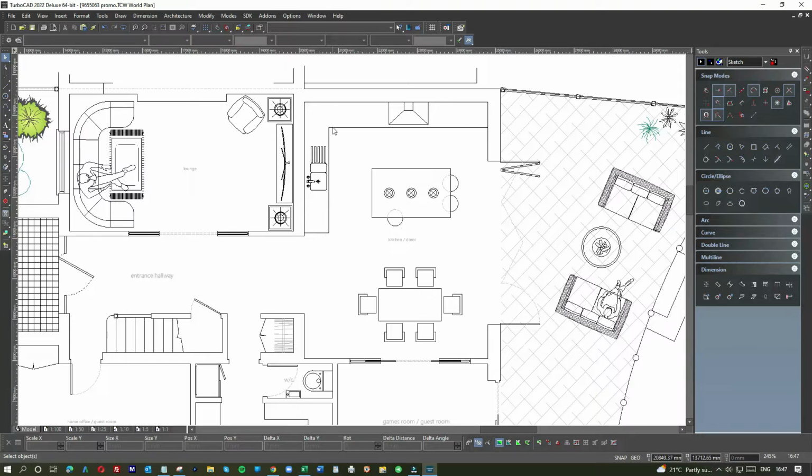At this point, these drawings are for planning. It's not a complete finished package, especially when it comes to the kitchen, which is going to be redesigned. Now we've got a decent island there. You can see the width on that. It's 1200, which means the units are only about half that size. So potentially you can add more units here to double up, or you can have half a unit, which is just shallow units, 300 or 400 mil, and you can then still get your legs underneath it. So either way, it has great potential.